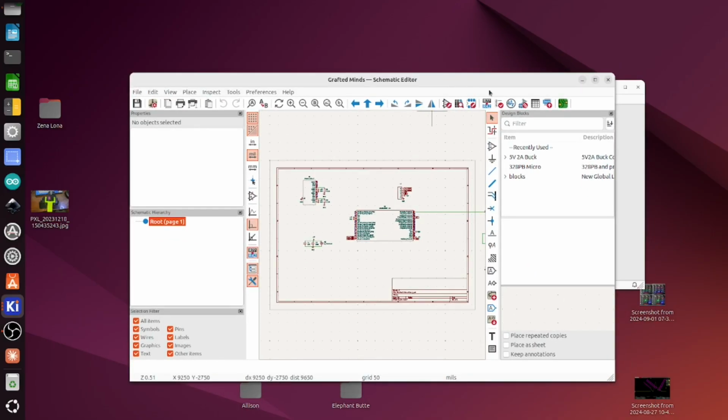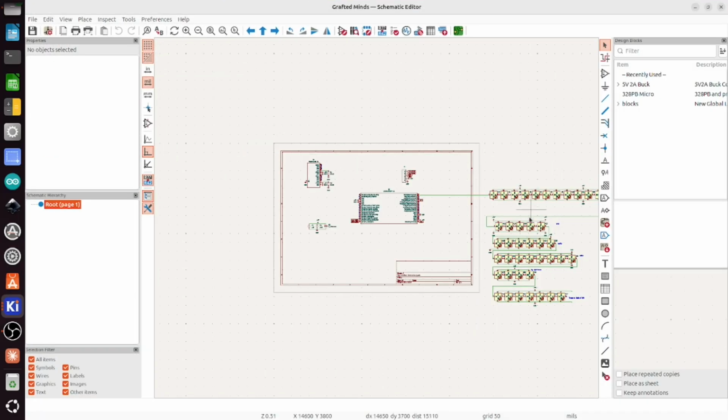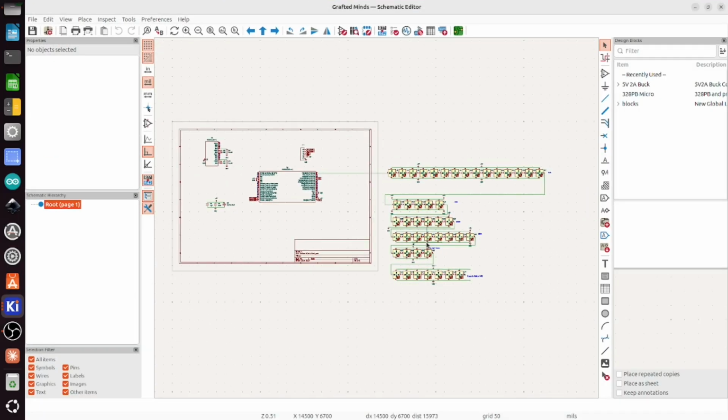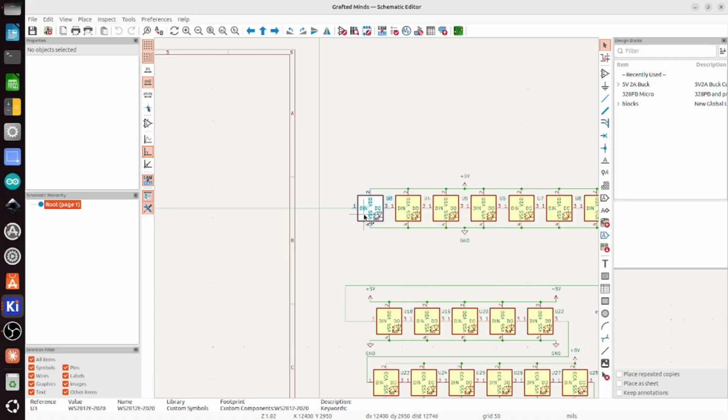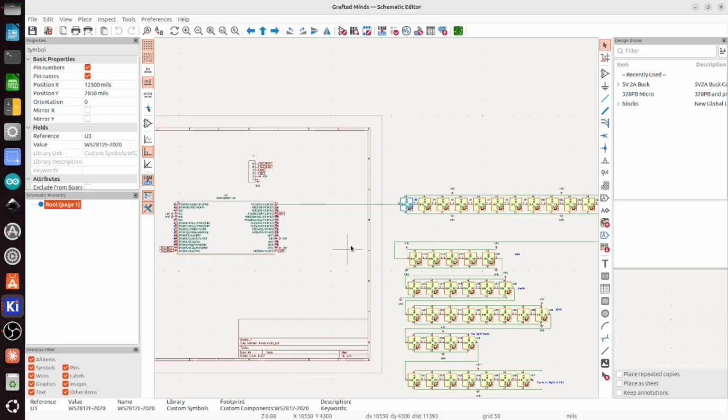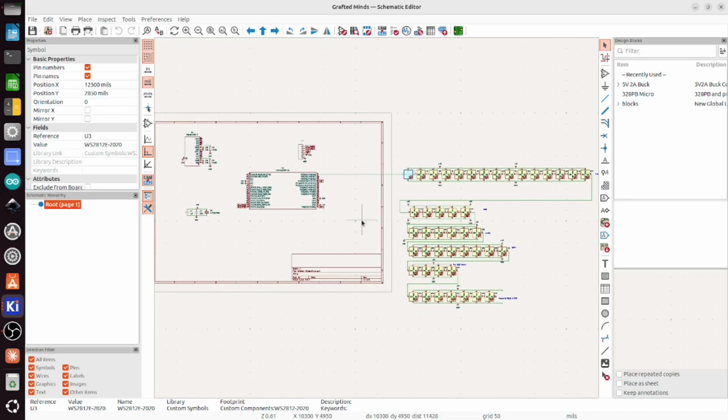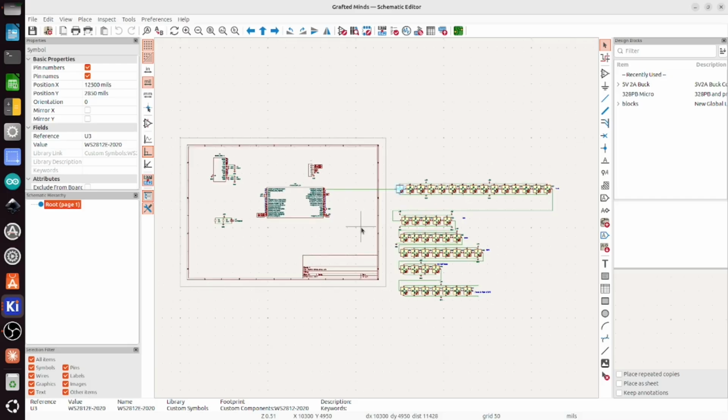So generally speaking, the way that this works, if you want to make a board with KiCAD, the first step is to draw a schematic, which often includes drawing some schematic symbols if KiCAD doesn't already have them. Or usually there's a library out there that you can import. Somebody else has already done the hard work for you, but nonetheless, I'll make a video down the road covering how to make schematic symbols and how to make board footprints.